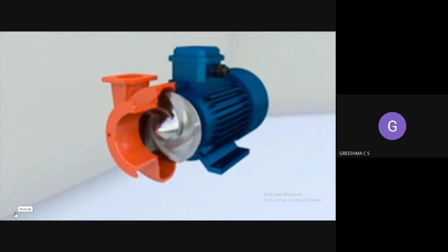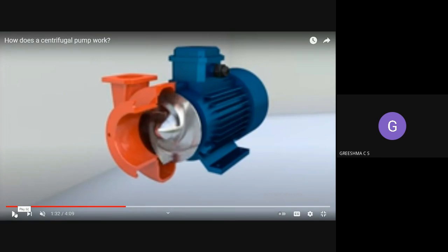See, it will be rotating like this. These veins initially will be rotating like this. So water will be passing through it, and then through this impeller, which means water is subjected to a centrifugal force. The torque will be acting. That is how the pressure energy of the water will increase, and water will be passing through the delivery pipe. Okay, so that's how it is working.